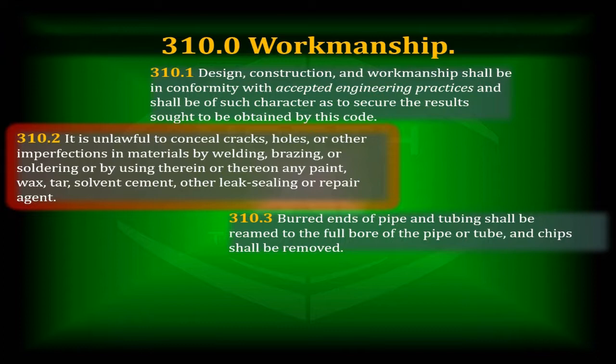That's got to be reamed off, not just with a wedge reamer that could possibly distort the copper, but an actual reamer. And when it comes to PVC, whether you're using a hacksaw or a cutting tool, oftentimes we're going to have those burred ends on there, the little shavings of PVC that can get up inside of the system. Of course, that's going to stop up any shut-off valves, aerators, whatever the smallest areas on your system are. That's where you're going to find those shavings stopping it up. So make sure that you're cleaning up your cuts after you're making them.